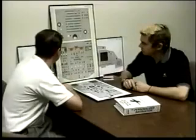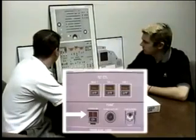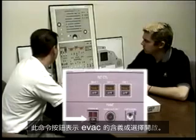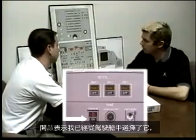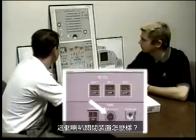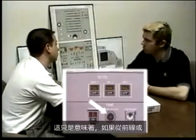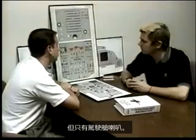EVAC. You have a red EVAC on the command button. Describe to me what this command button with the EVAC means, or selecting the on. EVAC means that an evacuation has been commanded. On indicates that I've selected it from the cockpit. What about this horn shutoff? That just means that if an evac is being commanded, either from the front or the back, I want to silence the horn from the cockpit. Only the cockpit horn, though.